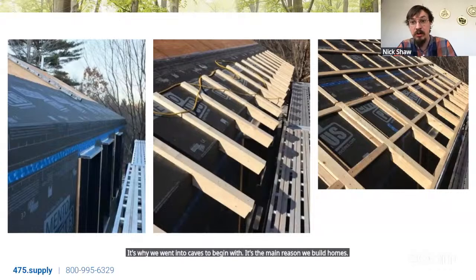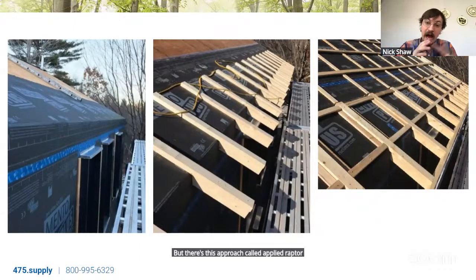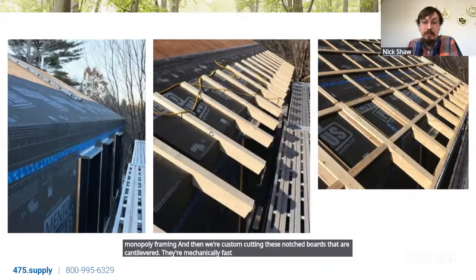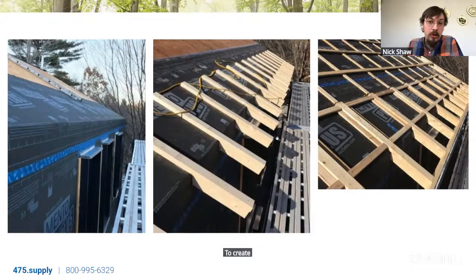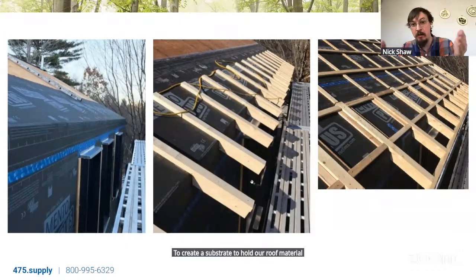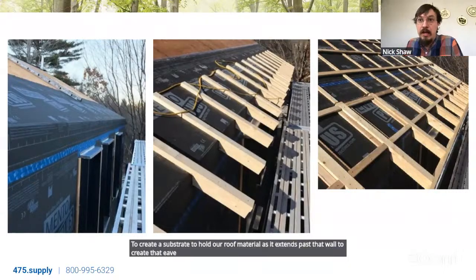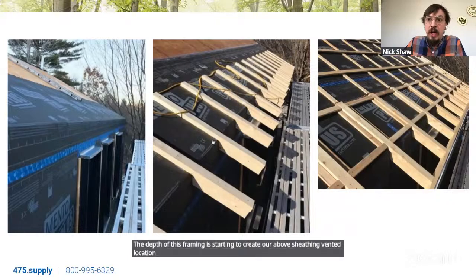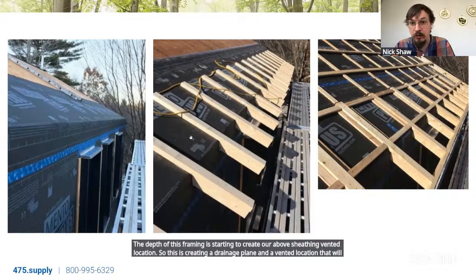But there's this approach called applied rafter tails, where we have the monopoly framing, and then we're custom cutting these notched boards that are cantilevered. They're mechanically fastened down into the top side of the structure, and then they stick out to create a substrate to hold our roof material as it extends past that wall to create that eave. And now the depth of this framing is starting to create our above sheathing vented location. So this is creating a drainage plane and a vented location that will be below our finished roof material.